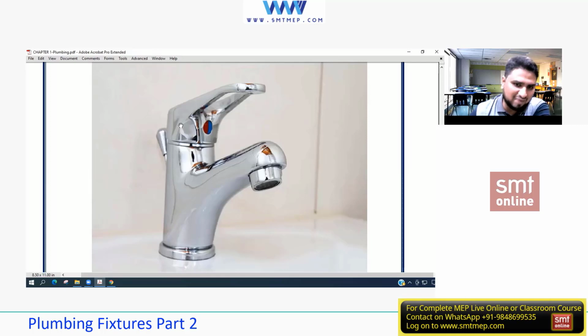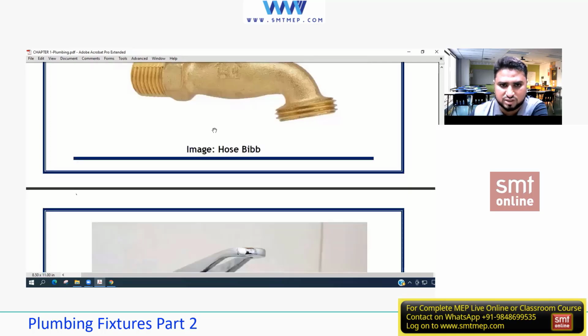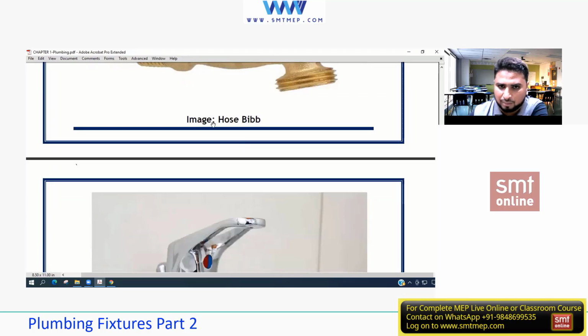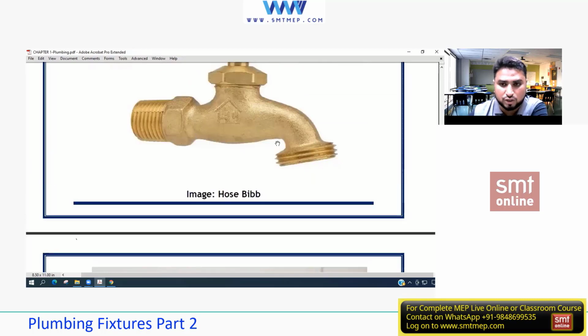Okay. So angle valve over here. Always remember, the most important technical thing is the difference between these. Wood might be demanding, here it might be demanding cold and hot, but water is again the medium. Here also water is the medium. But here, gate valve and angle valve. Always remember, completely open or completely closed, not in between, or else the gate will get damaged.